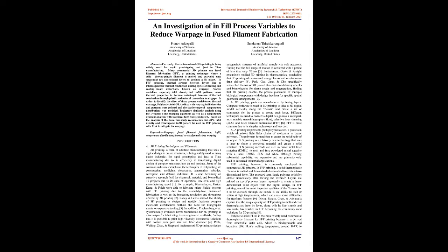Trajectory similarity analysis using the dynamic time warping algorithm as well as a temperature gradient analysis with statistical tests were conducted. Based on the analysis of the data, this study recommends that 30% infill density and trihexagonal infill pattern be used in FFF printing with PLA to mitigate the warpage. Keywords: warpage, fused filament fabrication, infill, temperature distribution, thermal stress, dynamic time warping.